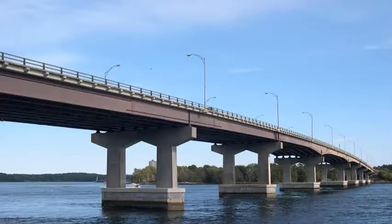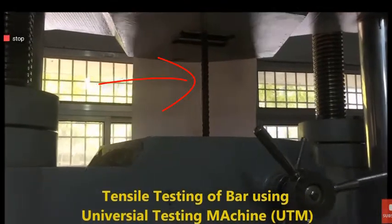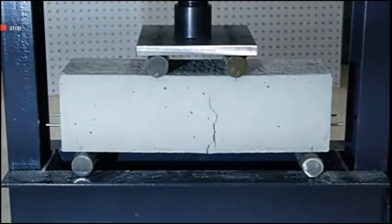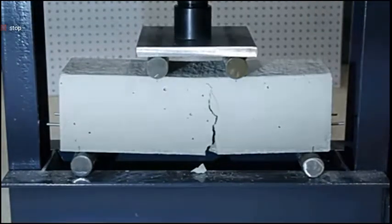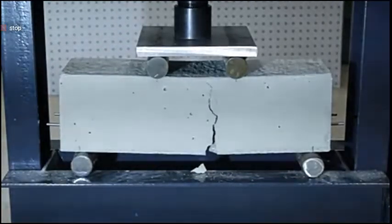Just like other structural elements, a pile foundation is tested for tensile and compressive strength. You take the reinforcements to the laboratory to test for the tensile strength, while you take a sample cube to the laboratory to test for the compressive strength. But these two tests are taken during the construction of a pile. But our main concern is the test we take after the construction of a pile.